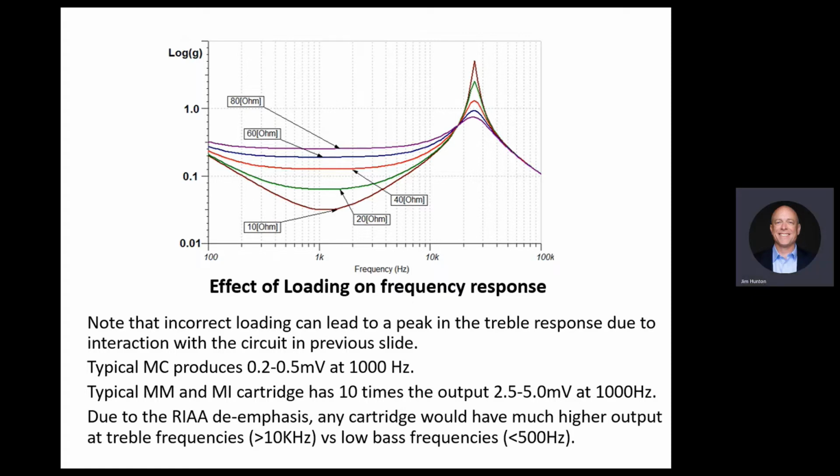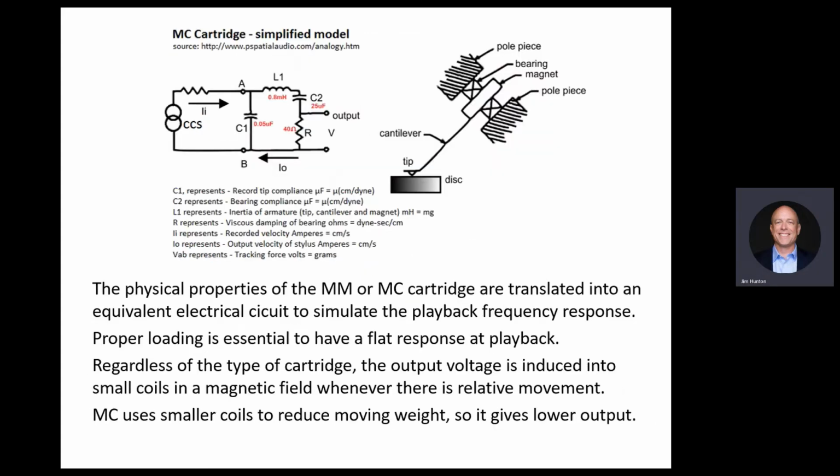Because when you put circuits with capacitors and inductors like this, there's a capacitor here, there's an inductor there. These are resonant circuits. They have a frequency and we can calculate that frequency, so they resonate at that frequency. Of course, the designer is trying to change the cartridge in a way that these parameters fall outside the audio band, so we don't have a lot of impact on what we're hearing within the audio band.